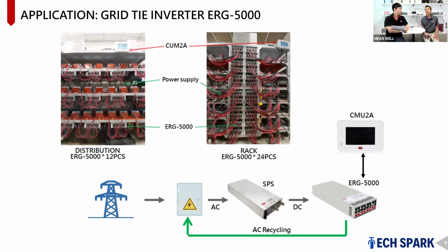Another one is connector and contactor testing, which needs testing and burn-in during production. Customers also use the ERG 5000. Instead of dumping the energy into a resistor bank, which wastes energy, it goes back to the grid. So a lot of component manufacturers and power supply manufacturers are assembling these units to save energy now.